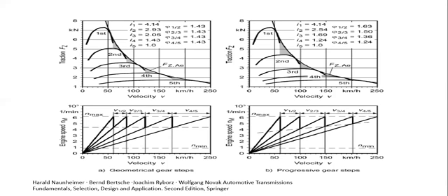For example, if we are considering a 10-speed automatic transmission, the gear step of 4 to 5 will be as small as the gear step of 9 to 10, but in the lower gears, the step of 6 to 7 will be as large as the gear step of 1 to 2. You can make a main gearbox with progressive gear steps, but it works well in high range only, while gear step 6 to 7 can't be too high.